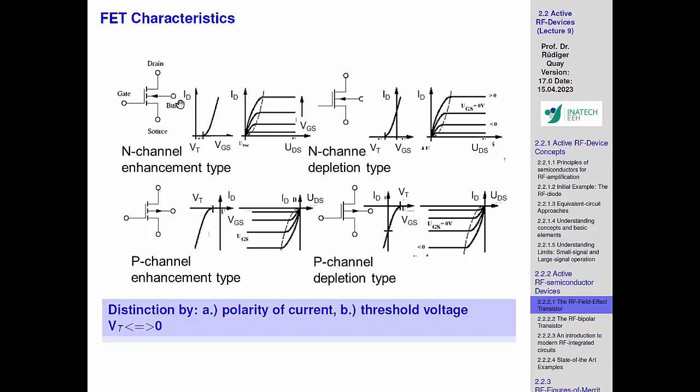So a lot of very good and fast RF FETs are also of this type. It depends a bit what type of device it makes. And the other thing where silicon is very advantageous, but I think I mentioned it, in silicon we have N conduction and P conduction, and they are similar. In most of the other semiconductors we don't have that. And generally the electron-based mobilities are better. In most of the devices, the N-type is actually the better RF structure.